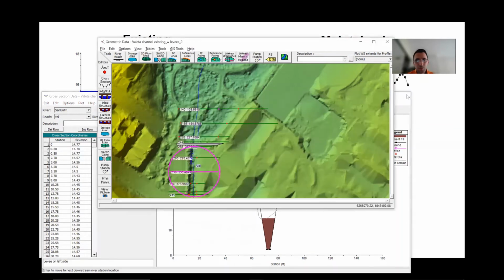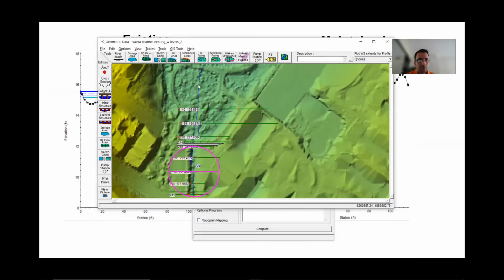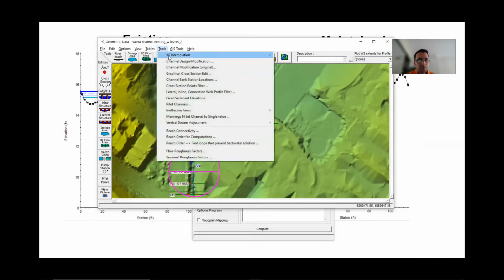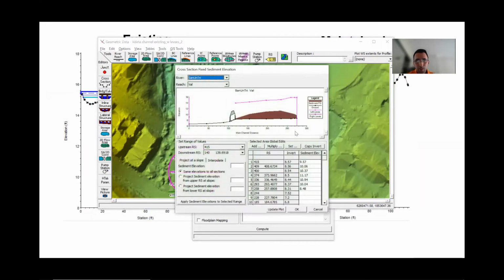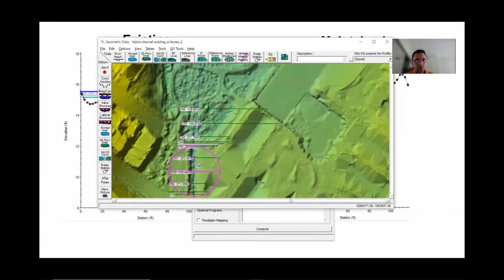So it's showing you basically the sediment window. If you do it, then I've replicated this sediment blockage in the channel. So I'm not working with something that is just earth, and it doesn't allow me to model this deck and culvert. So that's done. And now I have a geometry saved for my existing condition.